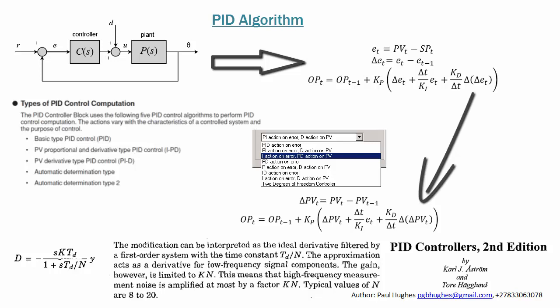I'm not going to try and pronounce the surnames, but in essence, what is done in most systems is the PV, or the term used in the derivative part of the PID algorithm, is passed through a filter. So I think this is basically a filter that kills all your high frequency noise. Now if you implement a PID algorithm without doing this, it can be shown that it can be very, very unstable for fairly small settings of derivative values.